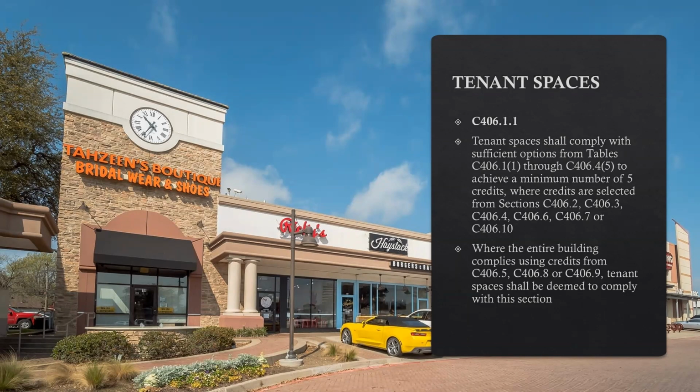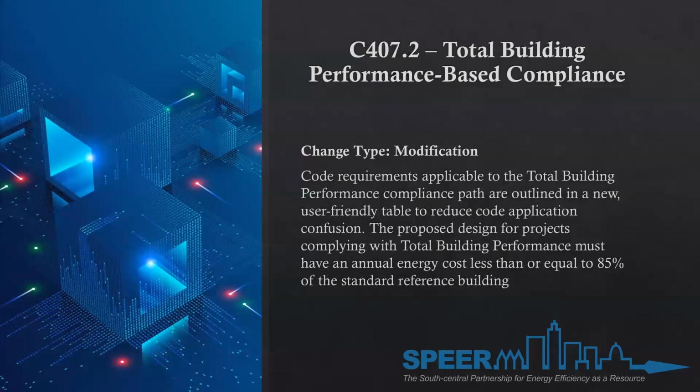And that's how they look at enhanced envelope performance: you're tightening the envelope, which will have the conditioned space stay conditioned longer, which isn't going to make these systems run again and again and again. So all these things tie back to you're just looking at lowering energy consumption.